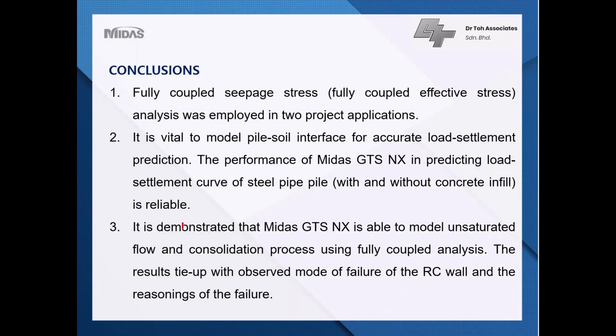So with that, I would like to draw the following conclusions. Number one, fully coupled seepage stress analysis, which we normally refer to as fully coupled effective stress analysis, was employed in 2 project applications. Number 2, it is vital to model the pile-soil interface for accurate load settlement predictions, in terms of the settlement and also the bearing capacity.